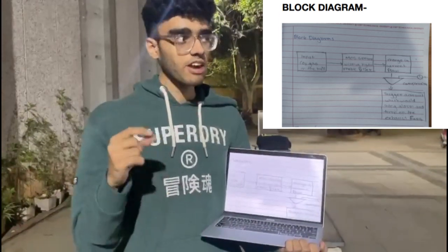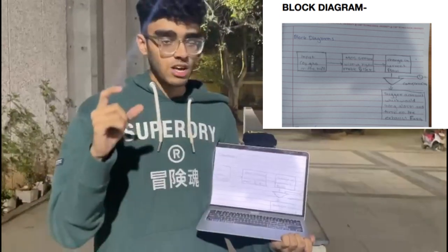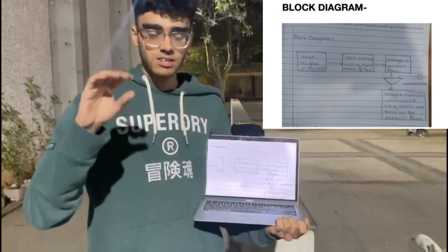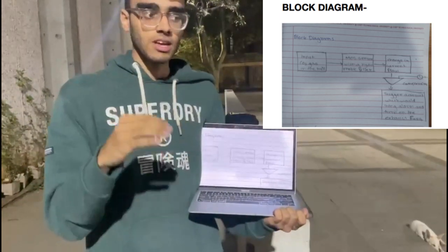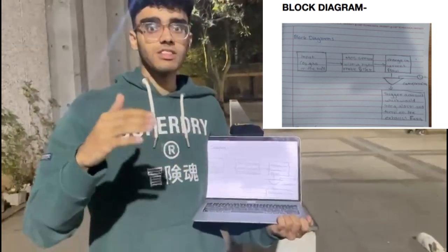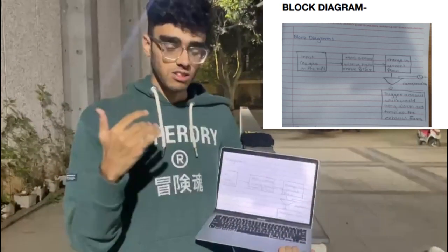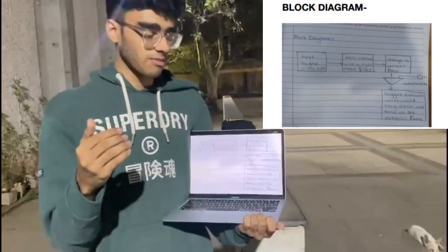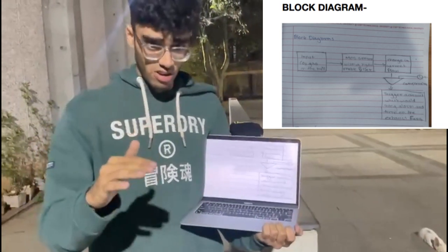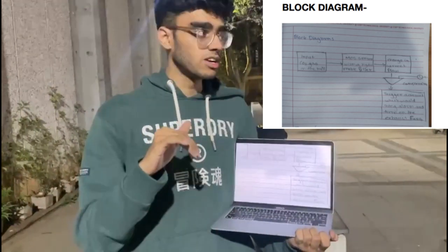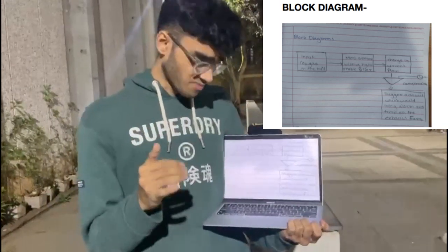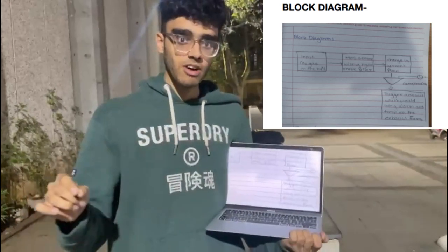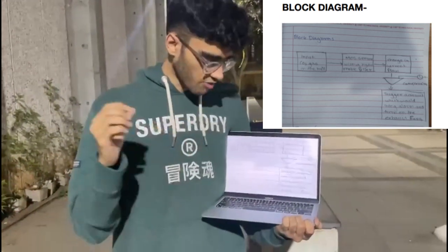The comparator will have an already set reference voltage. That reference voltage will be equal to or less than the voltage shown by the sensor when the ppm level is higher than normal human conditions. When the comparator reference voltage is lesser than the voltage input from the sensor, that will trigger the comparator to give out a digital 1 signal as a signal of on.